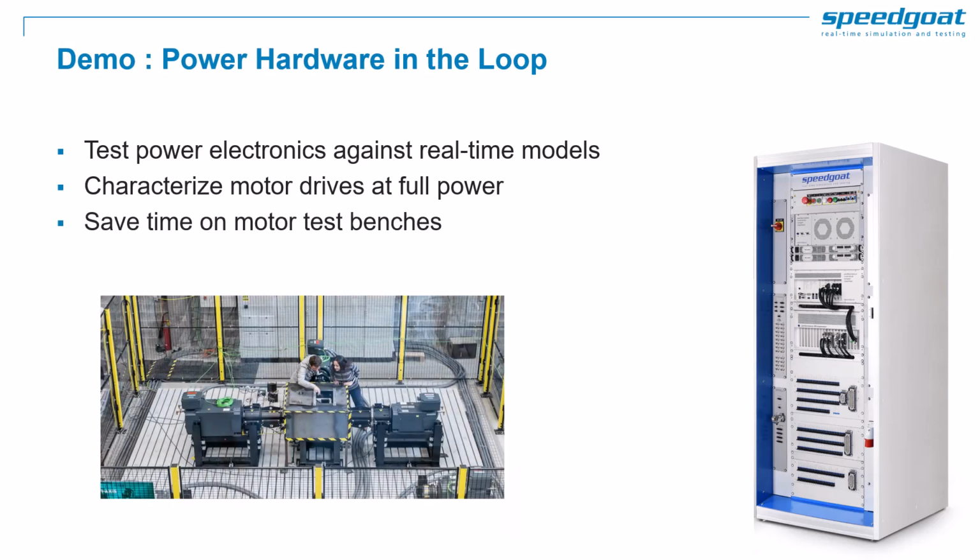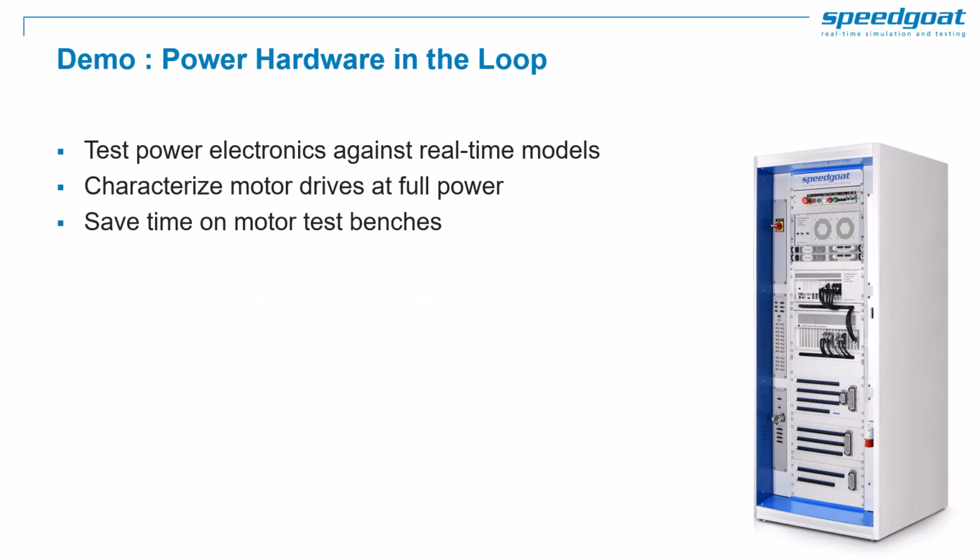Traditionally, you would require a motorized test bench to apply mechanical loads and to measure torque as well as speed. This type of equipment is expensive, and preparing a specific test can take hours or even days. In this demo, we'll show you how to test key functions of your motor drive, such as testing the overcurrent protection and setting up automated tests with predefined load profiles.